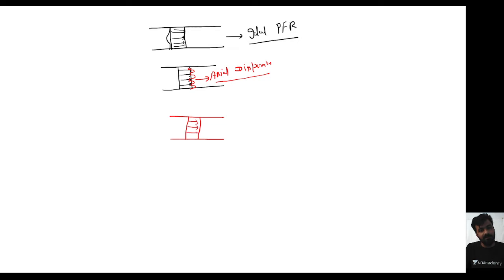So I am assuming this is the backflow profile. Here the molar flow rate of tracer will be entering, Fa at Z, and here I am assuming a small thickness dz. Okay, and here it will be leaving at Fa at Z plus dz, and it is bulk flow.